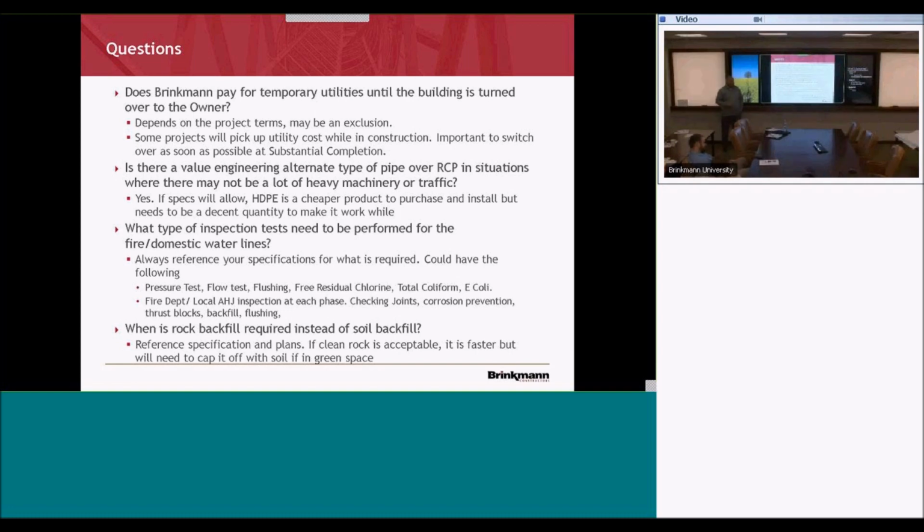So if you haven't seen a fire flow test, that water comes gushing out of that pipe. It's moving. It's flushing everything out of there. A lot of times they'll put up a device on there with a piece of metal that'll kick the water down. It also kicks out rocks. If there's rock in the pipe when they installed it, rock comes flying out. You can hear it when it hits that metal pipe. It makes a loud ding.